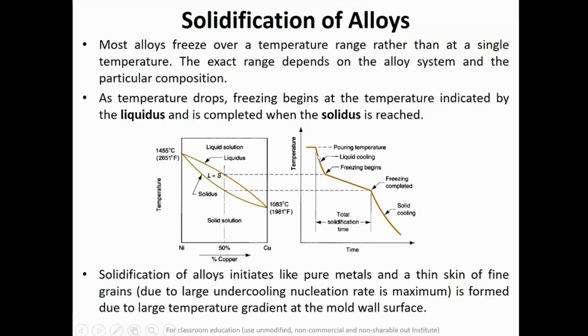the mold and it starts the liquid cooling, and at a particular temperature the solidification starts. Unlike in the pure metal, where it occurred at a constant temperature, that means the freezing was initiated at a particular temperature and at the same temperature it was completing. However, in this case, you can see there is a decline of the temperature, and after this freezing is completed, the solid is cooled down and brought to room temperature.